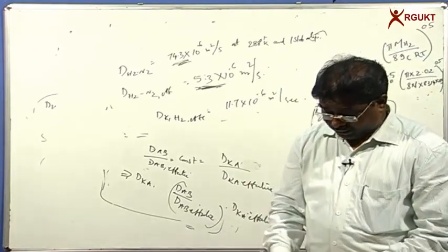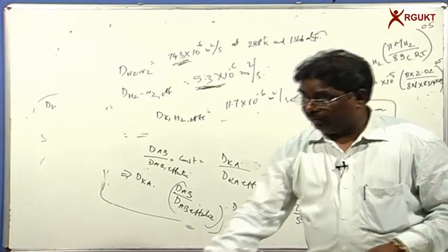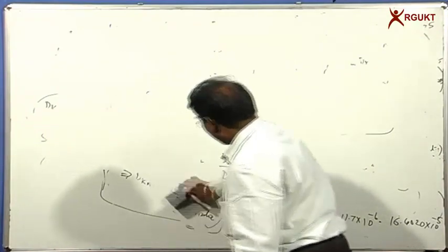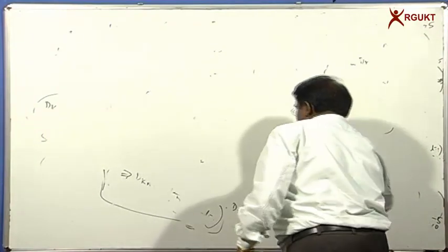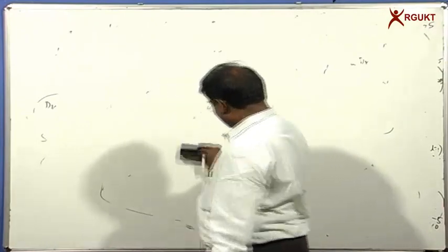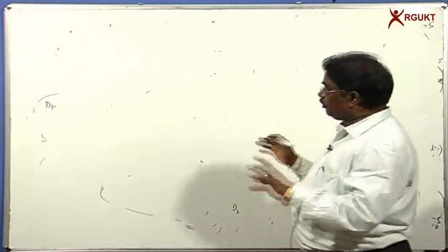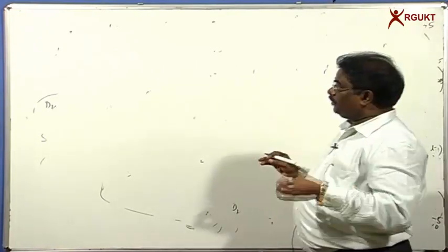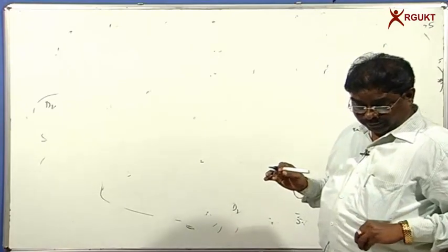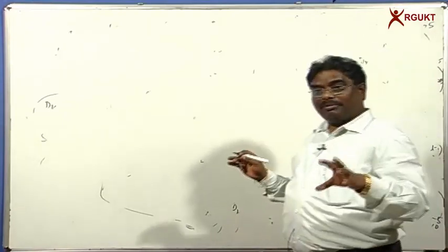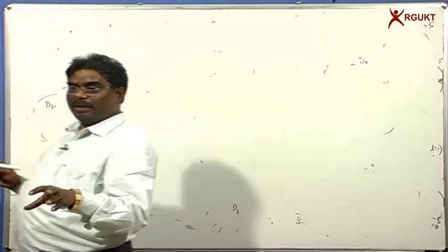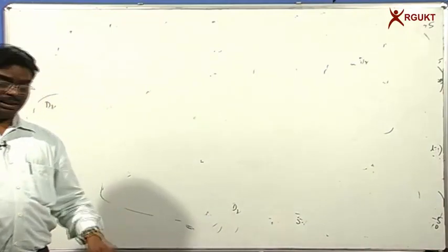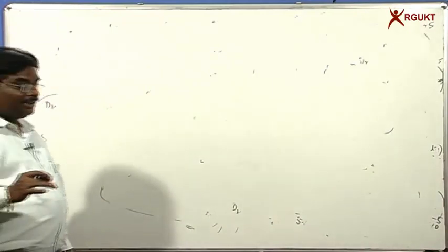Then the last thing which is left out is hydrodynamic flow of gases. If the pore sizes are very, very big, then diffusion will not take place; a convective flow is going to take place. A convection flow is going to take place, and we can also tell whether the flow is laminar or turbulent. If the Reynolds number is less than 2100, one can say it is a laminar flow. If the Reynolds number is more than 2100, one can say it is a turbulent flow.